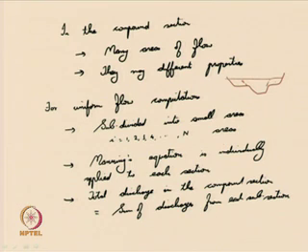Then Manning's equation is applied to each of these small sections individually. You can compute the total discharge in the entire compound section as the summation of discharges from each of these small sections. Like that one can devise the strategy.